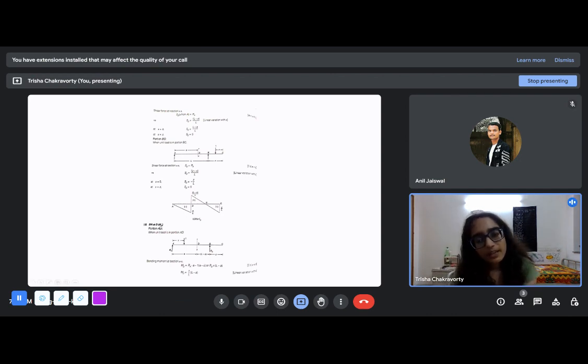And again, the bending moment diagram at D. Just keep noting that whenever we are talking about influence line diagrams, we are looking at two things. We have to fix two things, whether we are considering the moment or the shear force or the reaction, and the section at which we are interested. Here we are interested in section D, and we are interested in the bending moment.